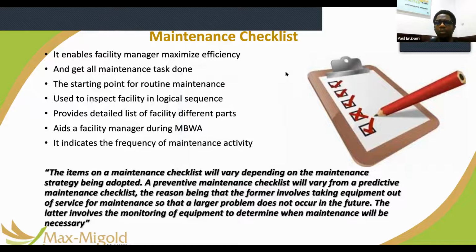Okay, thank you. Right, so back to that air conditioning example. I go into the indoor unit, I open it, take out the filter, step one, clean or wash it, and bring it back. I bring in a suction nozzle and suck the debris out of the internal drain. I bring in a vacuum, I suck up all the dust in the evaporator, right? I've put five steps already, okay?